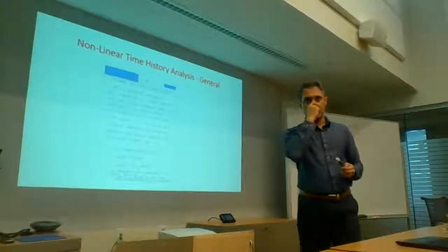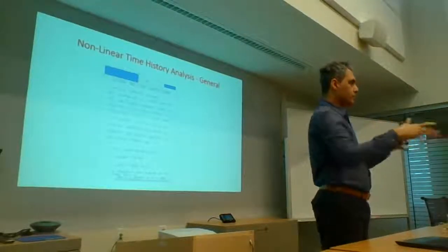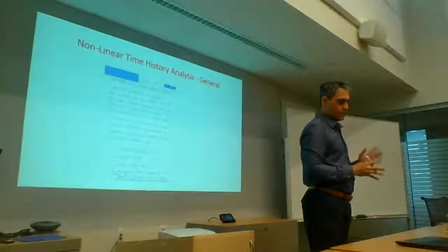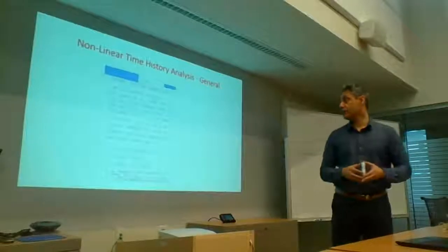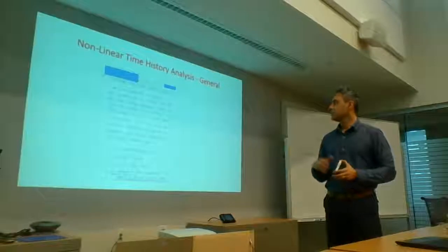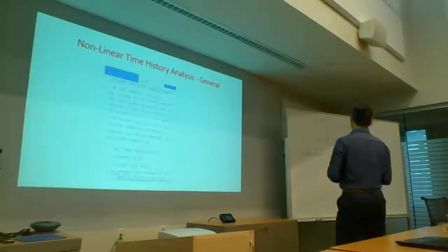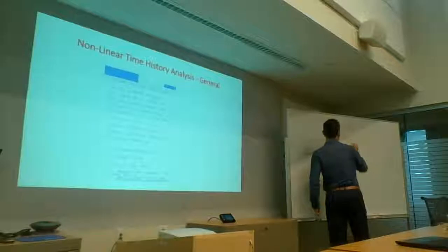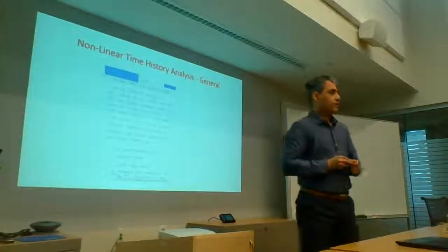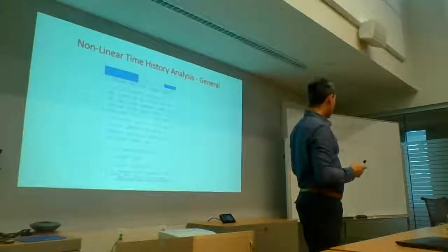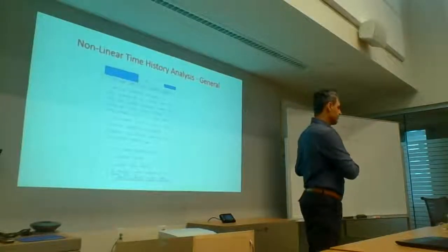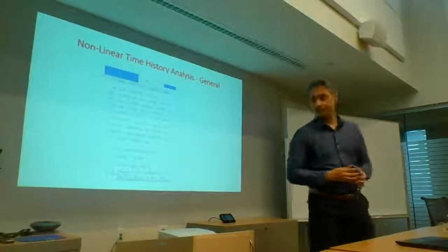When we were doing the response spectrum, because it was all linear, we could do other things. We weren't directly integrating these equations. In this case, except for maybe the fast nonlinear analysis, which I might touch upon in a bit, you really have to do this. Now, your ug or your forcing function is usually numerically defined, so the analysis has to be done in a numerical fashion. There are no closed form solutions available for this type of problem.